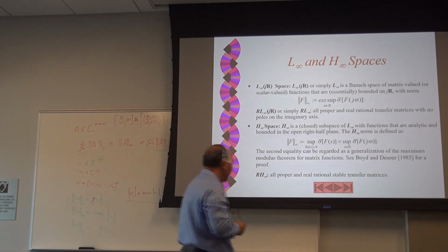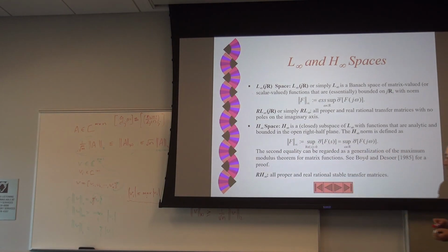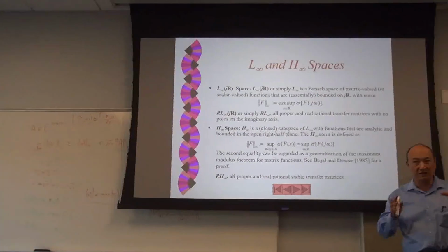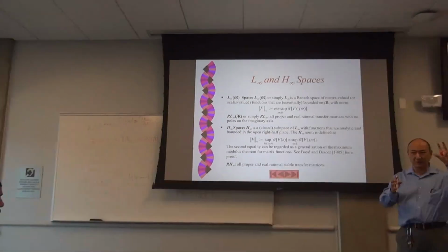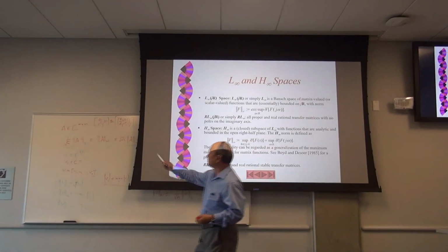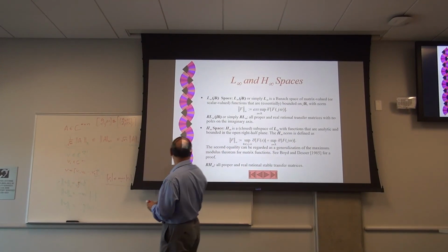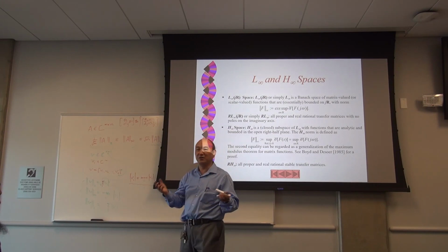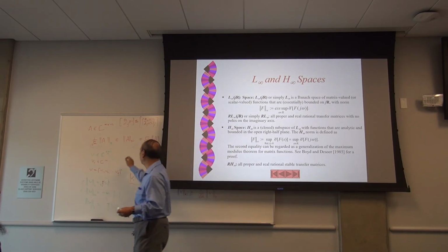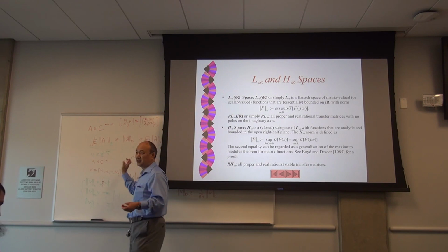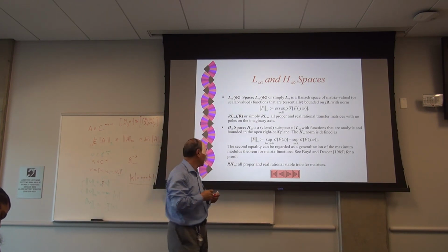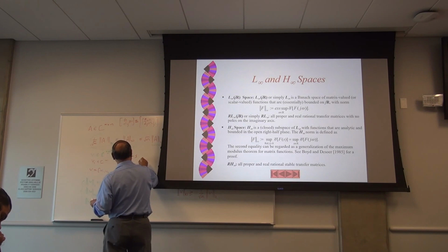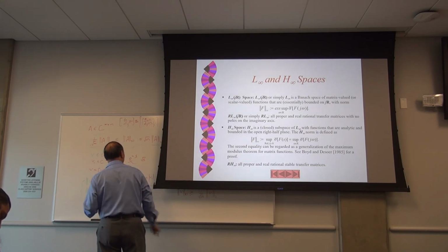So when we see what is proper, rational, okay, rational means what? It's two polynomials, okay? So these are polynomials, okay? Otherwise, irrational, like e to the power of s, e to the power of minus s. So this is an irrational transfer function, okay. Of course, square root of s is also not, so that's a fractional order stuff.